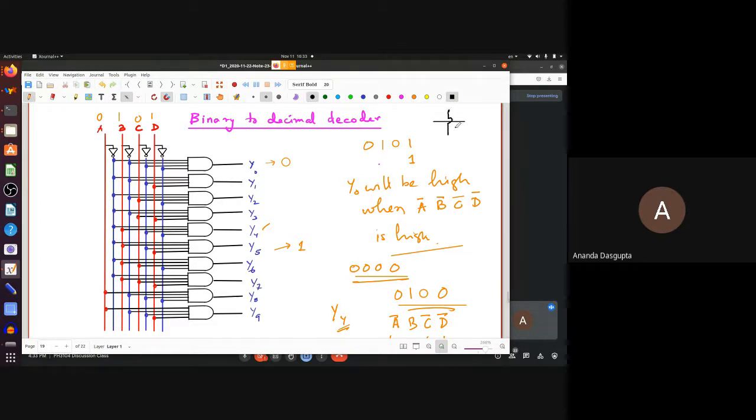If you want to show two wires which cross each other without being connected, you draw a bump. That bump actually is meant to signify that one of the wires is going either above or below the other wire. Okay? So you draw a bump like this just to ensure that people don't think that the two wires are connected. In analog circuits, usually it's a convention that when you draw something like this, you actually mean that there's a connection here. We often don't indicate the connection. The connection is supposed to be there.